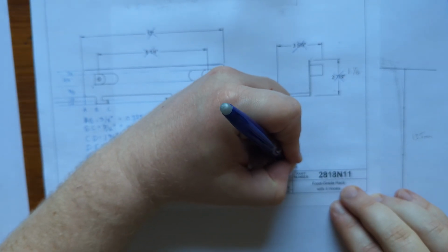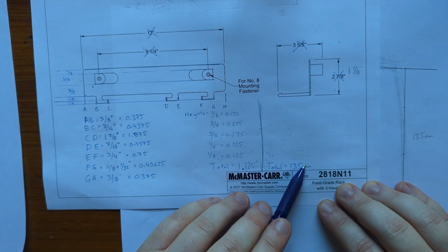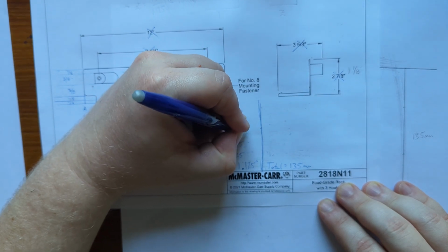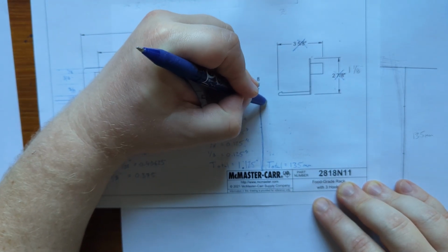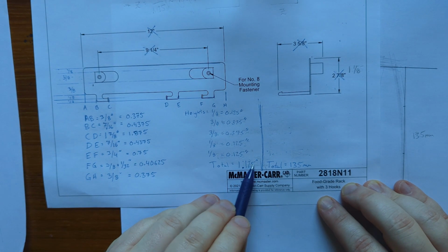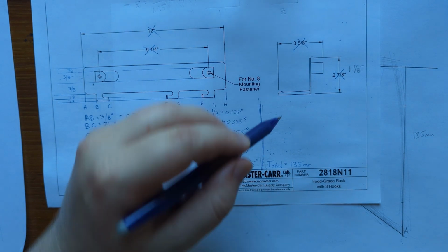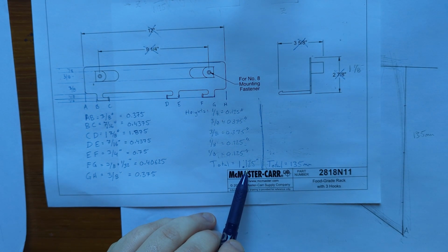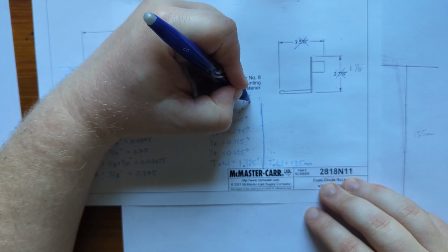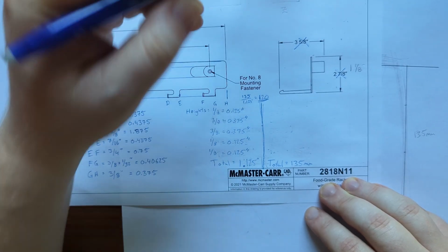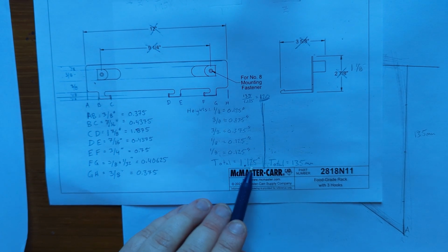My total is 135 millimeters. And again, it's totally okay to have a mix of units here, as long as we're staying consistent. In our real dimensions these are all inches, and everything over here is going to be in millimeters. So between here and here, we have some kind of conversion factor. To get from 1.125 to 135, we are looking at a conversion factor of 135 divided by 1.125. And that is going to give us 120. So to get from here to here, we multiply by 120. 1.125 times 120 is going to give us 135.